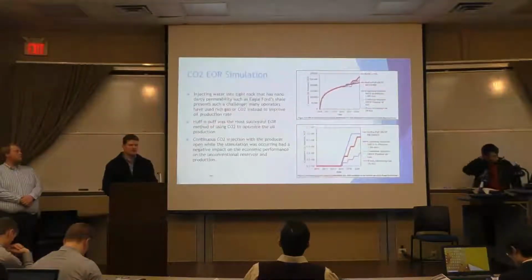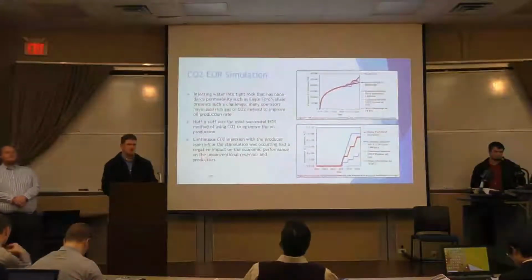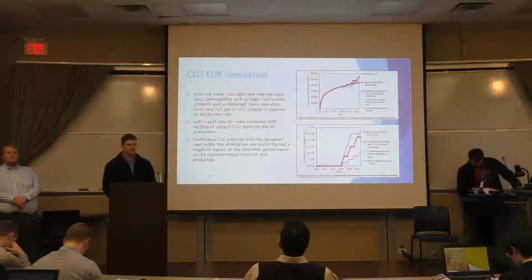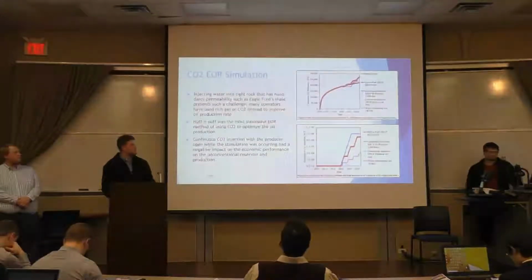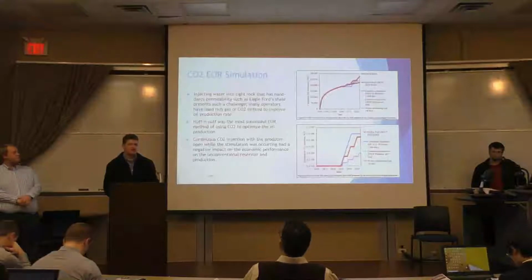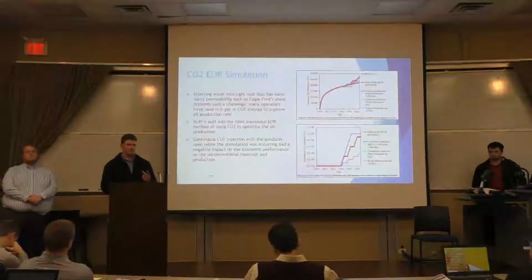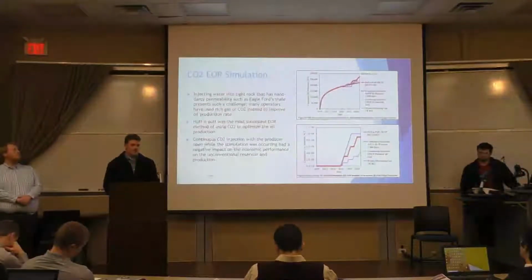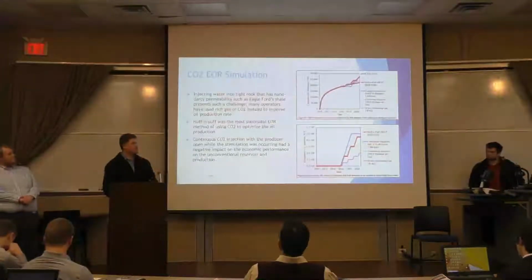With the conclusion of it, because water is so hard to inject at nanodarcy permeability, a lot of companies have been using gas injections, and during the simulation it was concluded that the Huff and Puff was the most successful because 2 Huff and Puff wells could be used for the continuous and the WAG, and it also used less CO2 injection than the continuous closed, which was the highest and gave you the highest recovery.